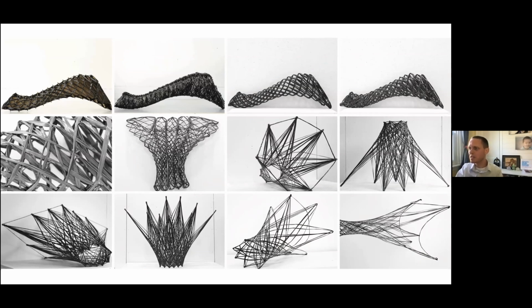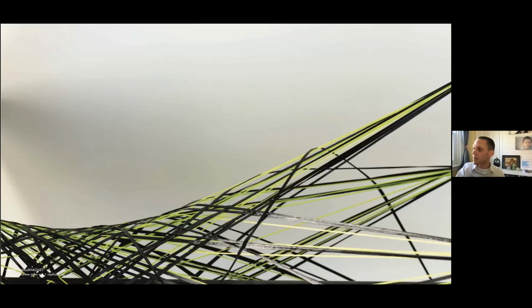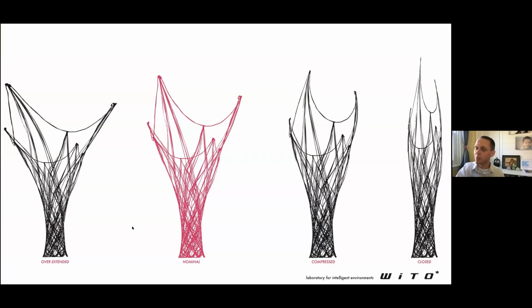These were some of the early studies that we had done, working with carbon fiber again. Through using digital tools, we're able to rethink how you can actually create a structure. This was a structure that I came up with where we wound regular yarn first, like this twine, wrapped carbon fiber around it so that it wouldn't slip, and then fired it in a kiln, and the string would just come off, so you'd basically have zero waste in the process. But the important thing about this project is that we had to get it to Costa Rica, and it had to be able to collapse.